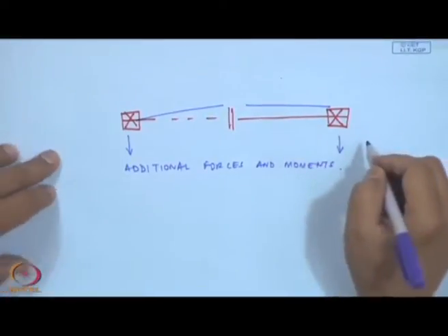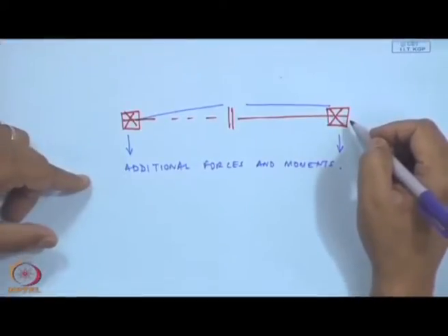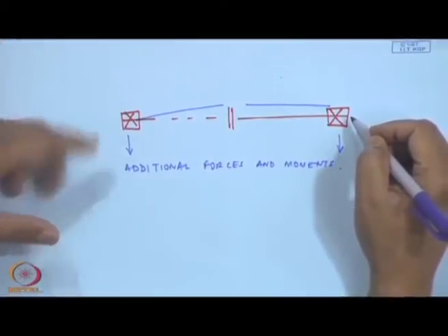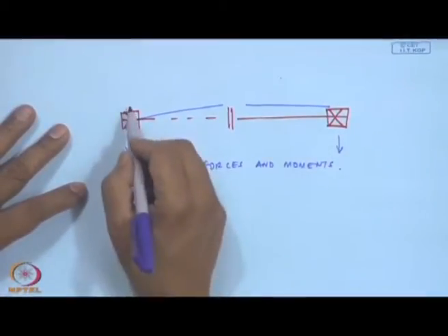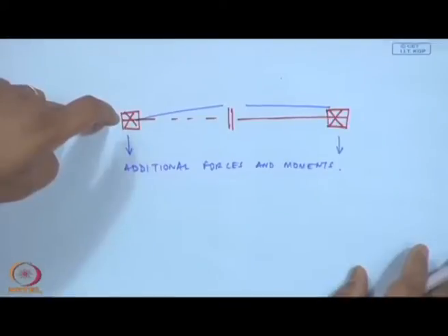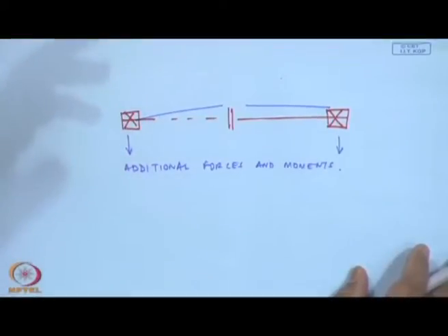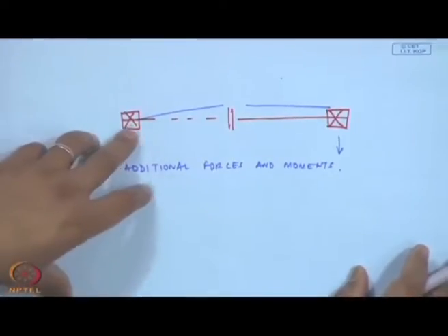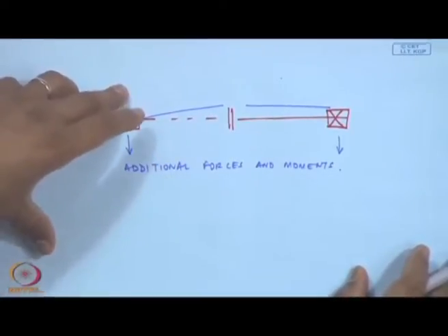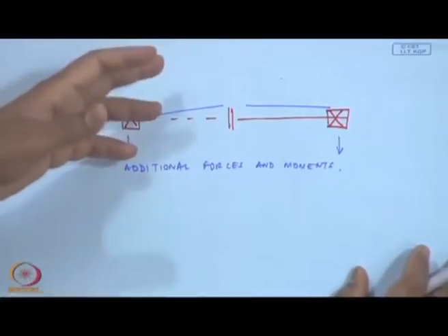So we will have a failure of the bearings because of misalignment, and then we notice a defect because there will be excessive vibrations at the bearings. But when there is excessive vibration of the bearings, people are misled and say that the bearing is at fault. The problem is that the misalignment created a fault in the bearing, or, as we had seen in the previous case, unbalance which went undetected created a problem at the bearings by giving excessive loads or fatigue loads. So bearings are going to fail.